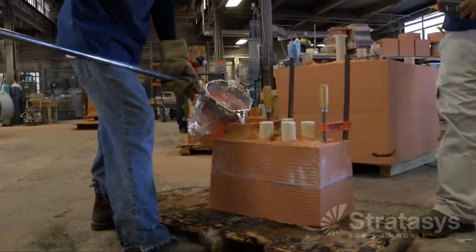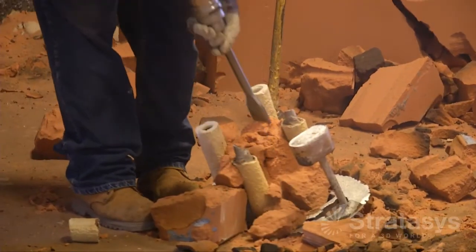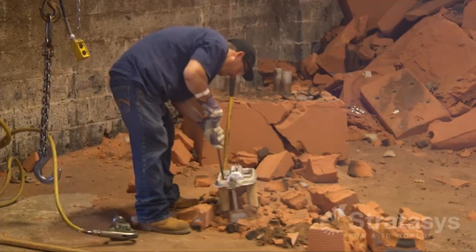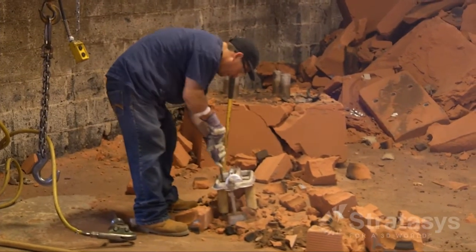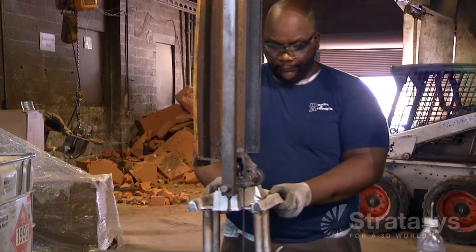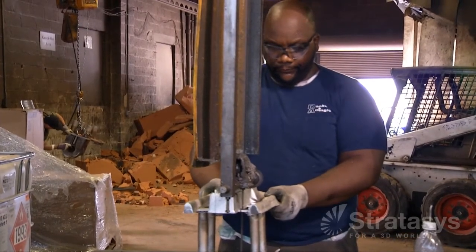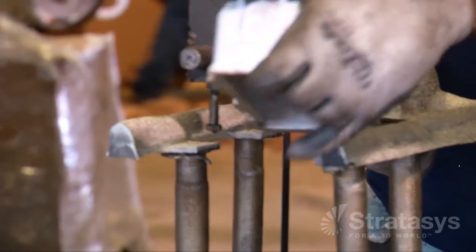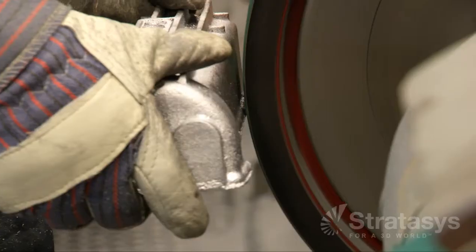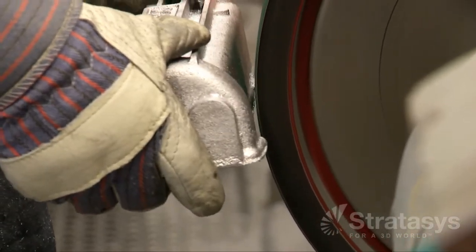Molten metal is poured into the sand mold. After cooling, the sand is removed with vibratory machines or through hand processes. Sandblasting may be used to remove any residual sand trapped in the cast metal surface. The raw metal castings then go through secondary processes, including gate and runner removal, drilling, sanding, and machining. These secondary processes can also benefit from FDM.